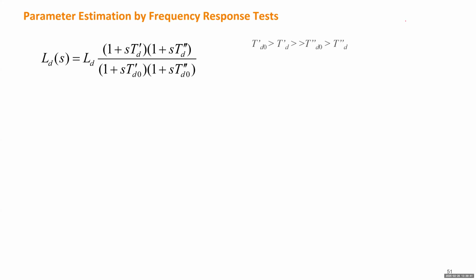So we already know this ordering, right? Which means if we consider the reciprocal of each one, that will be opposite. So this one will be the smallest one, and that one will be the largest one. And each of those will be either poles or zeros of this transfer function.